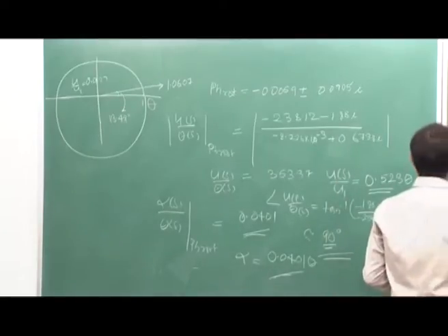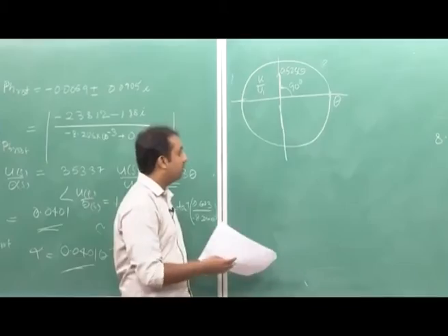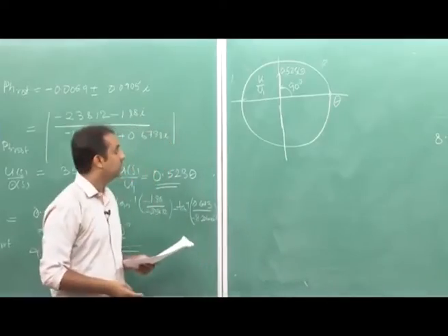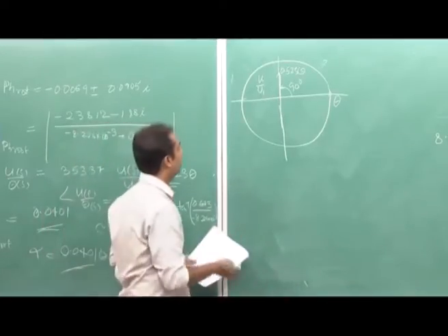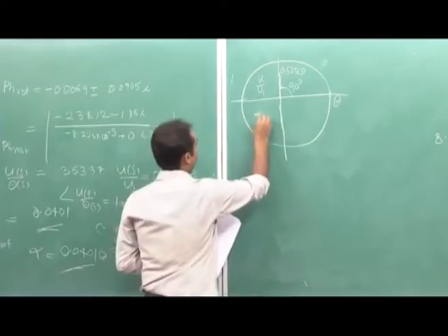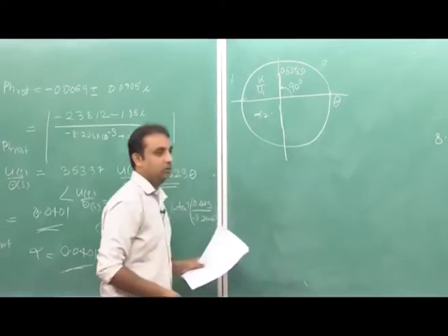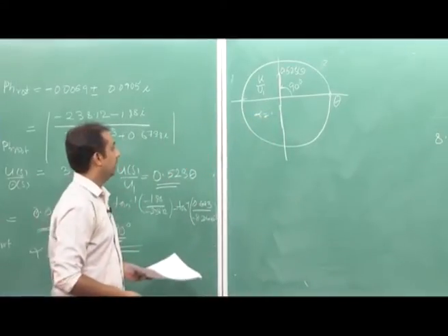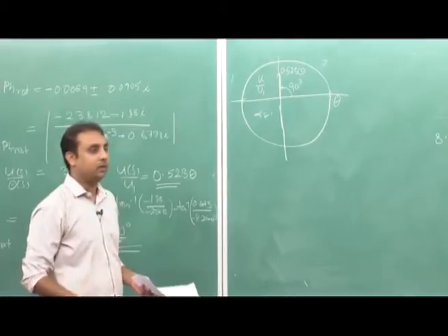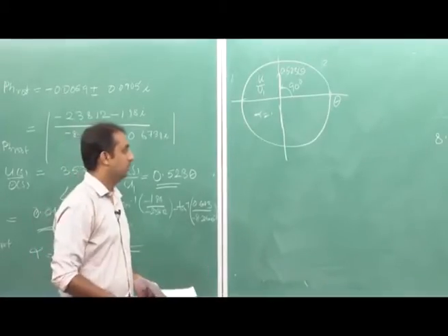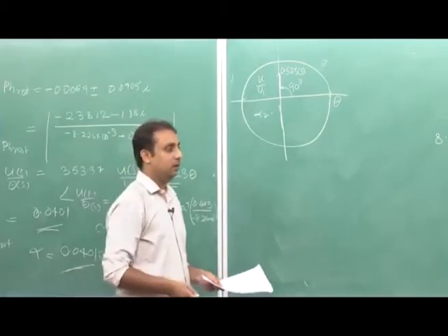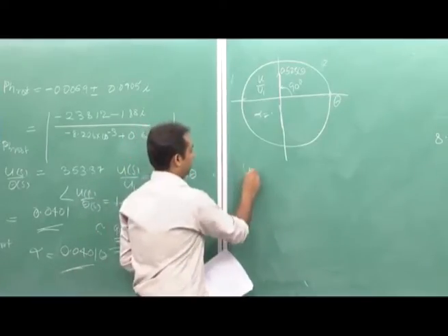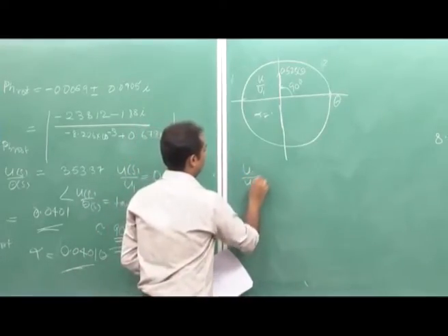Now, the information which we get from mode shapes is this: in the case of phugoid mode, since alpha is very small, we can say that for phugoid mode approximation, alpha remains constant, whereas for short period mode, u upon u1 was very small.